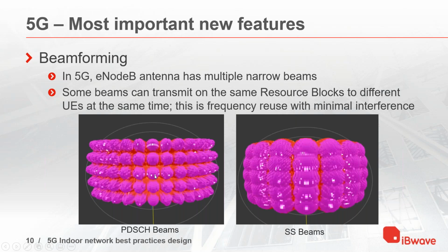So you do want to point in the general direction where you want to have your users. If you don't, the majority of users will be exposed to your worst beams, worst as in the worst quality, with the least amount of gain and the higher side lobes. So that is why you still want to down tilt your antenna in the correct direction.